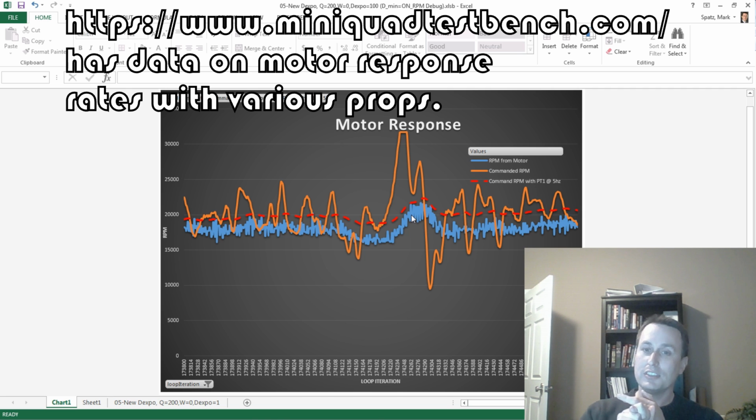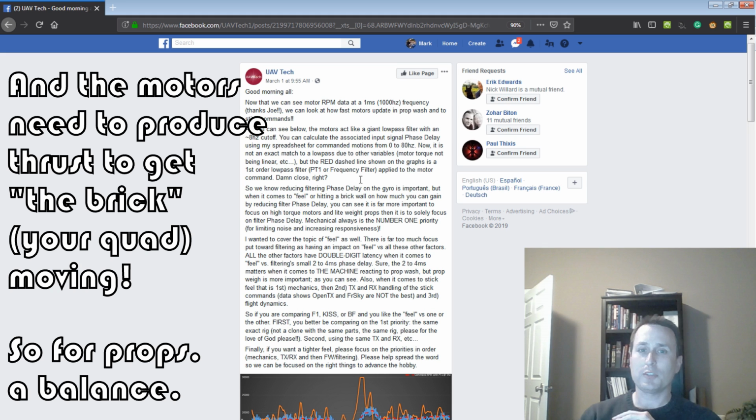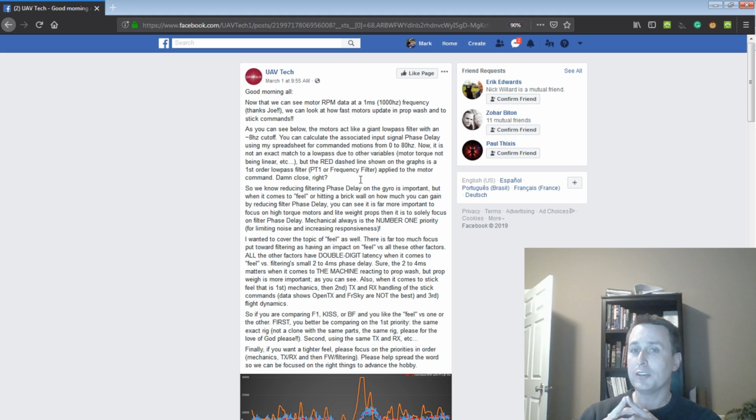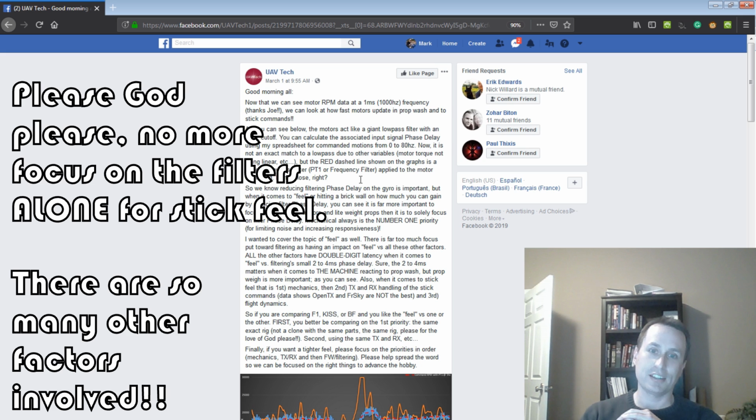That's key first. I made a post on this on March 1st on my thoughts where people need to really focus their attention when it comes to prop wash handling and stick feel. I know I'm big on filters, and they are important, trimming off as much phase delay as we can because it offsets the entire gyro signal back, and it does make a difference in prop wash, gaining that couple milliseconds of time and reducing that latency. However, it is definitely not the biggest factor, I would even say, for prop wash, and secondarily, it is way not the biggest factor for stick feel.